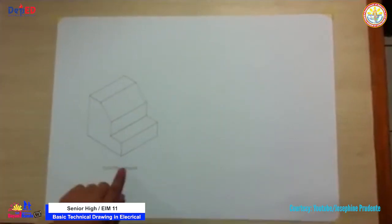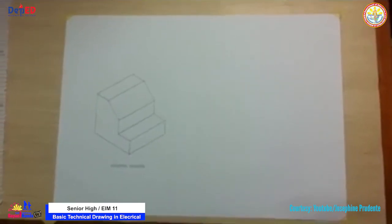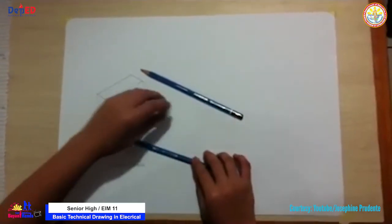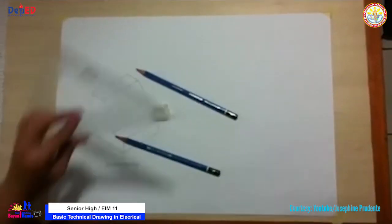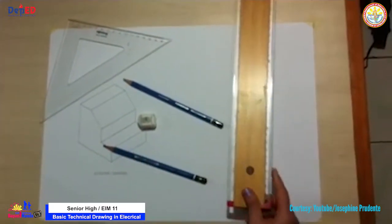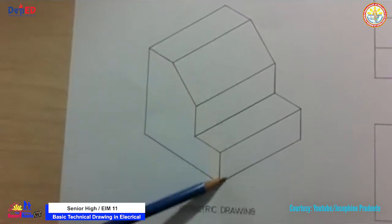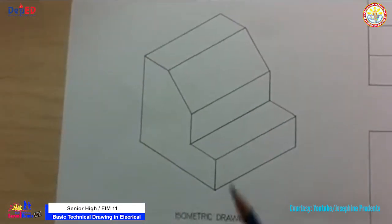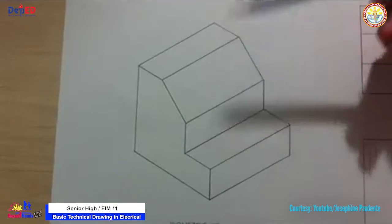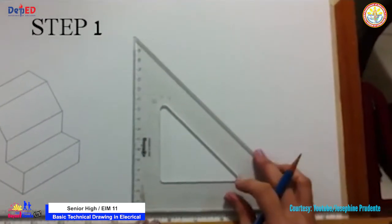Here, you will see an isometric drawing. What we want to do is to create the three views of orthographic projection. But first, let's make sure that we have the requirements: drawing table, pencils, eraser, 45-degree triangle, and the T-square that we will use for this task. First thing we're going to do is take a look at this object. This is going to be the front side. This is the right side. And this is going to be the top. Let's start. Draw the visible feature of the front view.